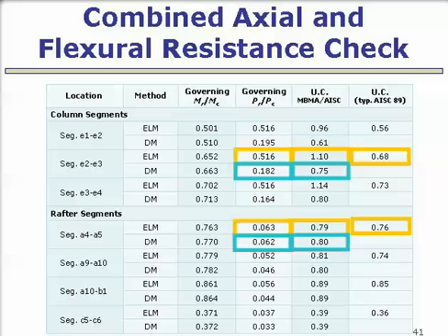With the direct analysis method, since we're really nowhere close to being a stability issue in this case, when we're looking at a non-sway failure, 0.182. We put everything together. We get from the effective length method a unity check of 1.1. So that violates the requirements somewhat, versus the 0.75 that I showed you.